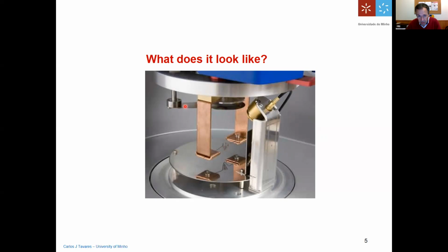Normally we have here a shutter. It can move back and forth, so we can protect the substrate holder, because initially we might not want to start the deposition immediately. We just want, for example, the particles to thermalize and have sufficient energy. After a few seconds, we will open the shutter. We also have here a quartz crystal balance, which will monitor the film thickness.